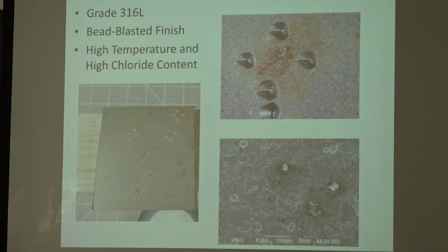There were a lot of windows, so they had to block the windows, blast, and put a lacquer on the surface. And what the lacquer does, it prevents the chloride from coming through the surface. It doesn't block the oxygen and the water, so moisture will go through just a little lacquer. But the idea is if we keep the chlorides out, I forgot to say this was by the ocean, then you don't start that pitting corrosion again. So chloride really had a big role in growing the corrosion pit.